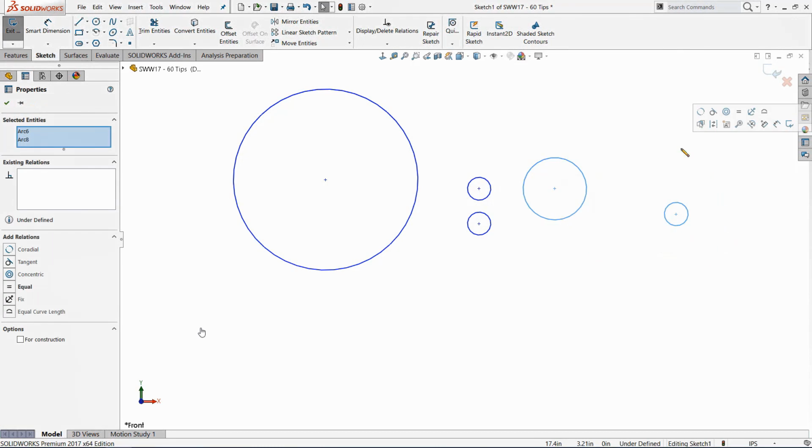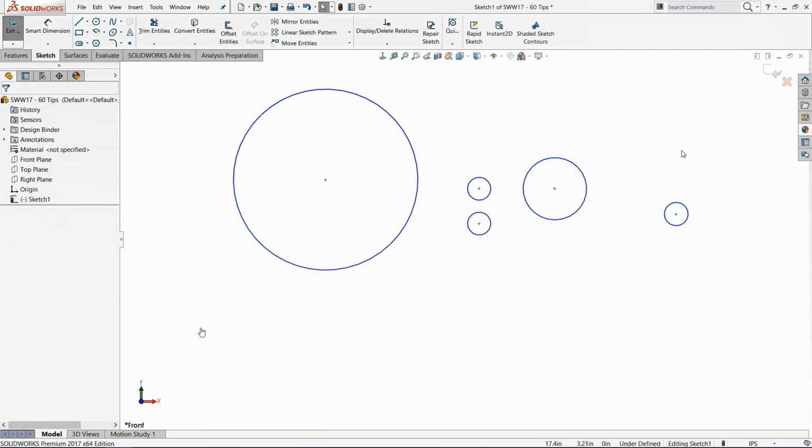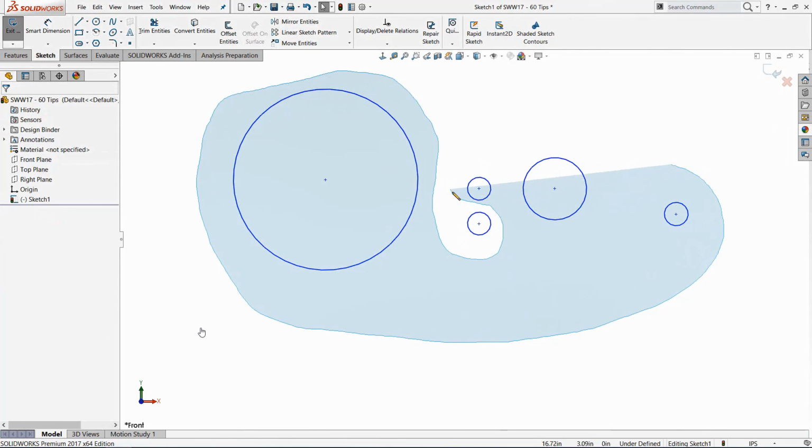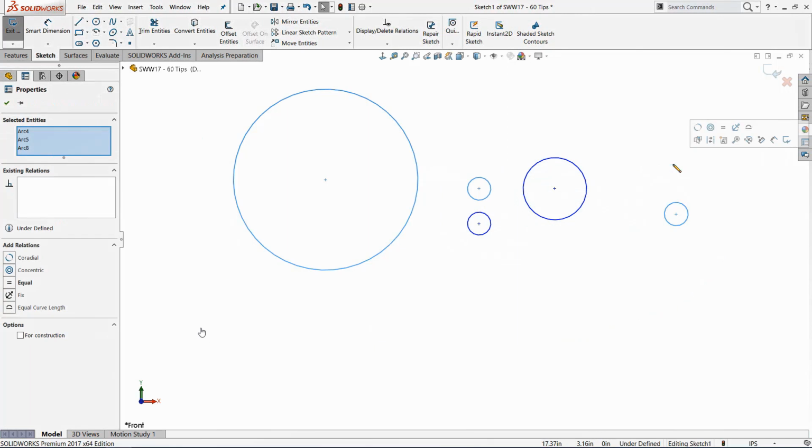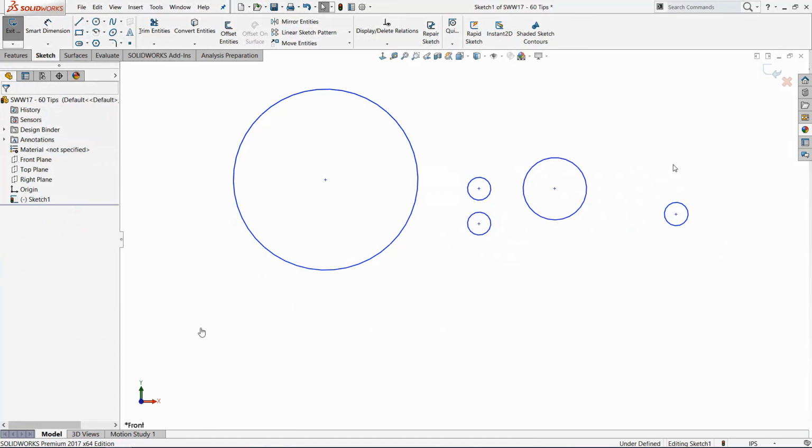I could have done that with a box select, right? That's not too impressive. But what is impressive is when you start to make these really complicated ones, like I want to select everything but these two guys. You can't do that with the box select. So you can get a lot of granularity there in the way you can deliberately pick things and realize that going from left to right or from right to left will act differently when you use these tools.